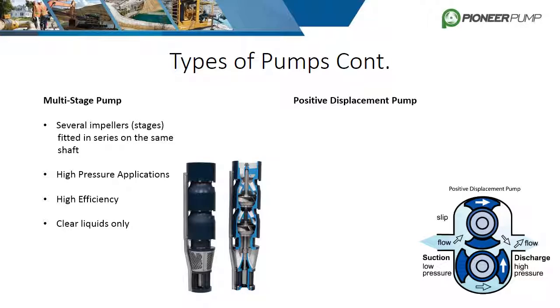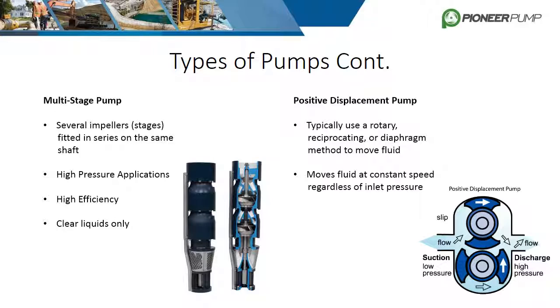Positive displacement pumps operate with a series of working cycles. Each cycle encloses a certain volume of fluid and moves it mechanically through the pump into the system. Depending on the type of pump and the liquid being handled, this happens with little influence from the back pressure on the pump. They are used in a wide range of applications, from services where a specific amount of liquid must be moved into a system to heavier duty services where the liquid is simply too viscous to be handled by a centrifugal pump.